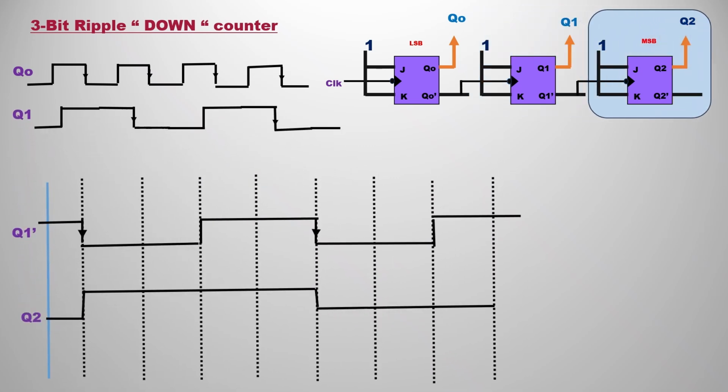So that is the same thing that I have done. Keeping aside Q1, because Q0 and Q1 are our outputs, next we are going to find Q2. If you observe, for Q2 the clock is Q1 bar, so we are going to have the clock transition on the falling edges. Like that you can see over there for Q2. I hope you know how to do that.